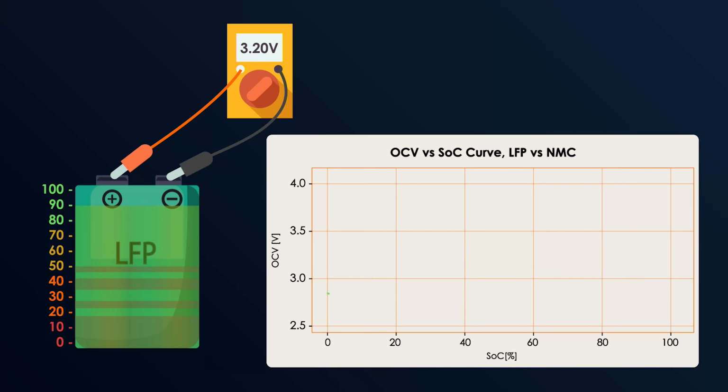They are the reason we battery engineers have grey hair and a twitchy eye by the age of 30. I'm one of them. From 90% all the way down to 20%, the voltage is almost a perfect flat line. It stays parked around 3.2 to 3.3 volts for almost the entire cycle. Is this an 80% charge or is it 90%? We don't know, our volts don't know.